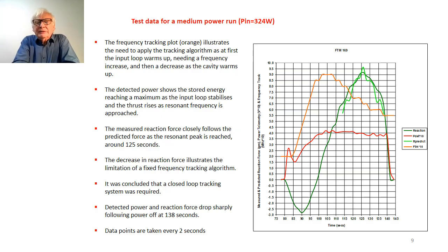What we've done here is show the effect of the manual frequency tracking algorithm rather than a closed loop frequency tracking system, which would be essential for any flight use of this thruster. You can also see, of course, the very quick drop-off of thrust at 138 seconds when you turn the power off.